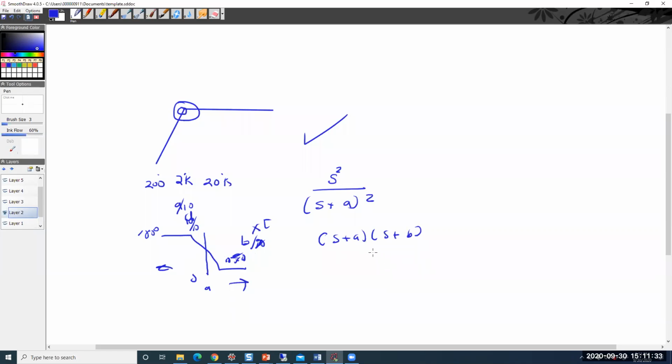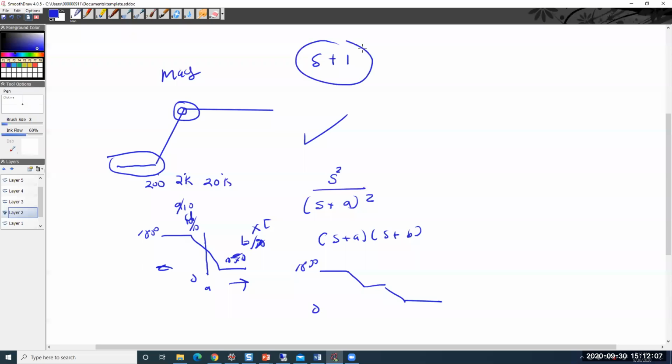And then it could be really far apart where the phase did something like this. And if it's a low pass, it starts at 0 and goes to minus 180. Some common mistakes on magnitude: although it's possible to have a Bode plot like that, low and high pass filters do not do that. You would need a pole, a zero, not at 0, to get that kind of action.